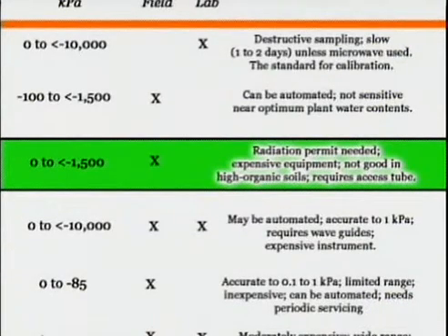The neutron probe technique does indeed have to be calibrated back to our gravimetric water content, so that when we have a certain neutron probe reading, we know the actual content of water being held in that soil. But that's something that would normally be done at the time this technique of soil moisture monitoring was being implemented.